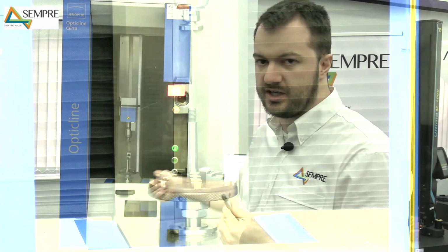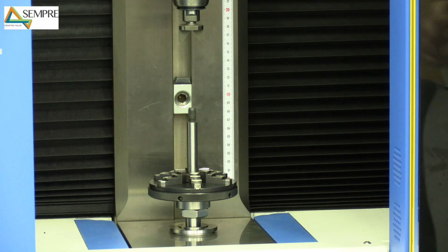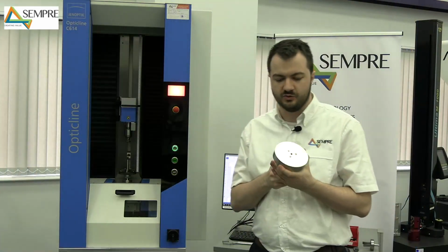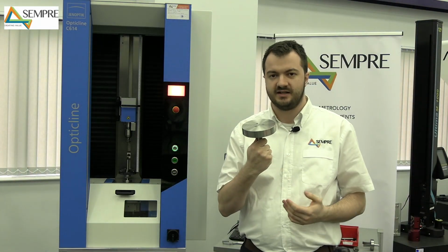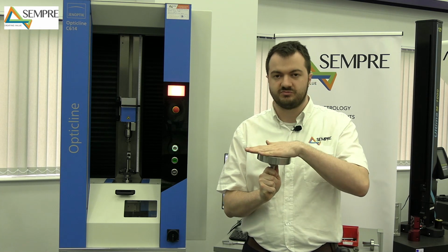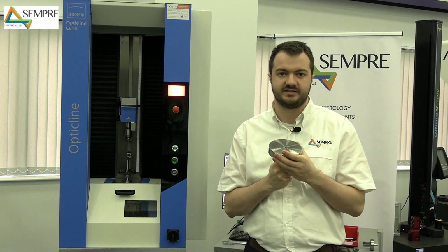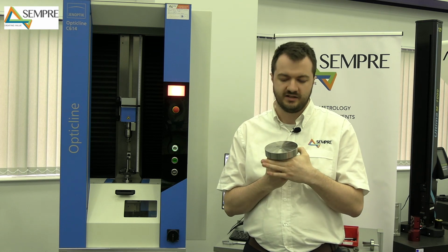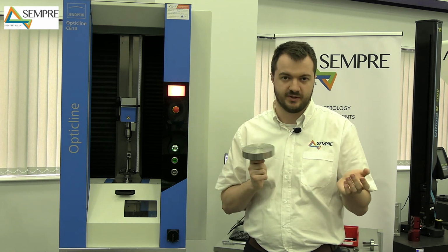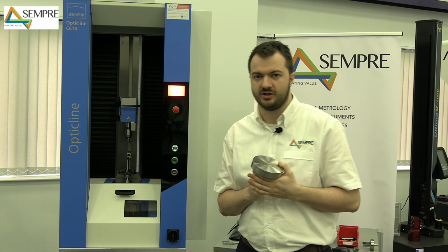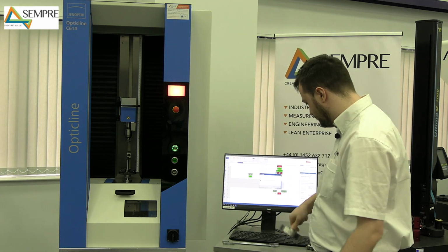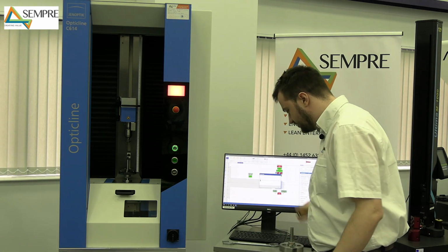And this is a 6-jaw chuck for the Opticline. And there are lots of options for centers. So for other parts where there's no center at all, you could just use a flat plate. And a flat plate will just, you rest the part on there and it will rotate. And it just uses the friction between it and the part to hold it. This is good for valve seats or bottles or anything else you can think of that has no features like that. For any domed parts, you can use female centers.